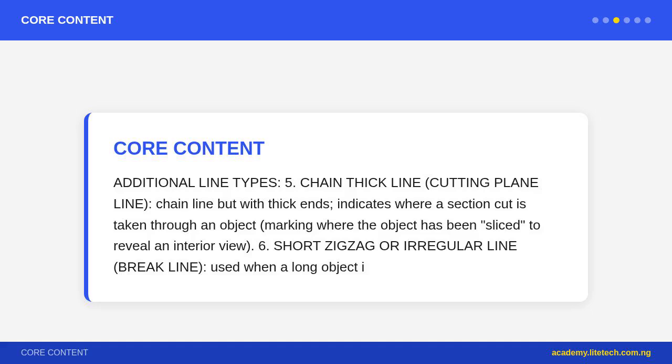Keep the pencil at about 60 degrees to the paper surface, lean it slightly towards the direction of travel. Keep pencil points sharp, a sharp point produces fine, accurate lines.